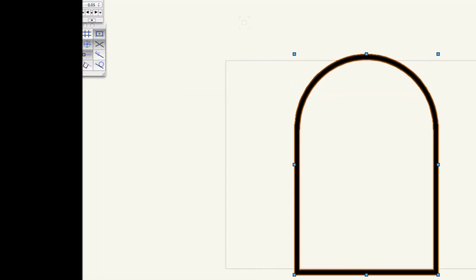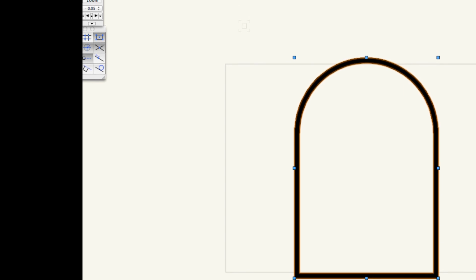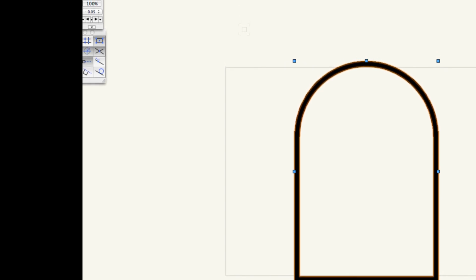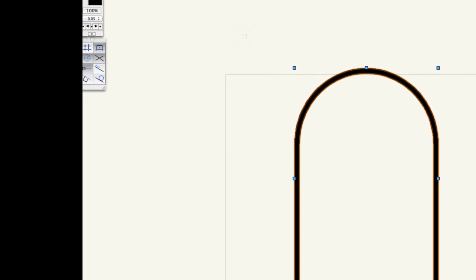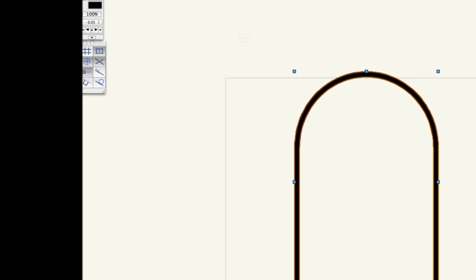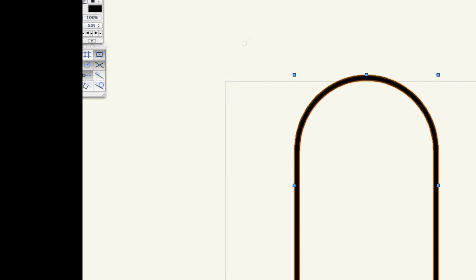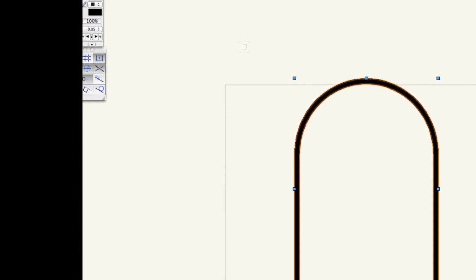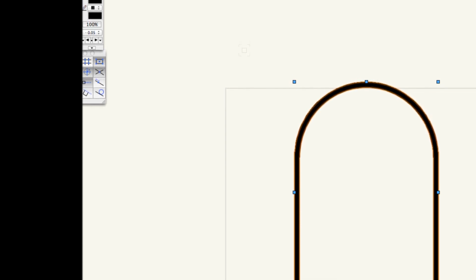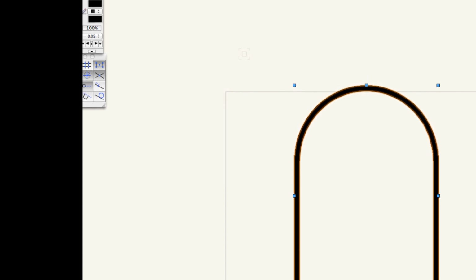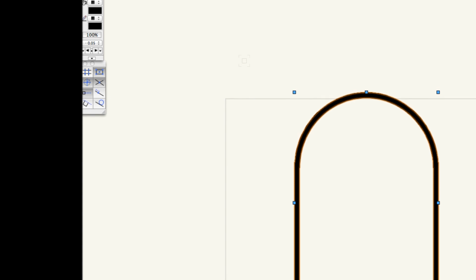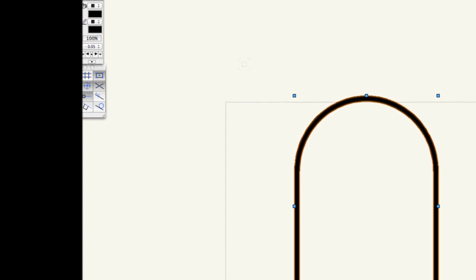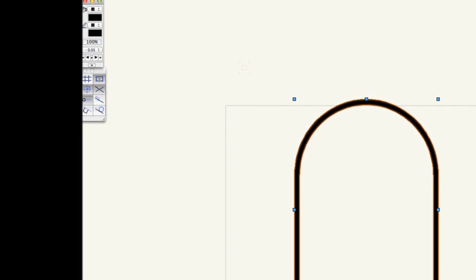The last task of the day was to look at how we can make a wall seem to represent a wall by using colour. So going to the attribute panel, we can change the fill of the wall to be black, and this is what we ended up with. It's looking a nice black and white contrast, and it clearly defines what is the solid object. We can also change this by using hatching, which is another selection, but instead we use solid here, as it will be simpler to make a plan.